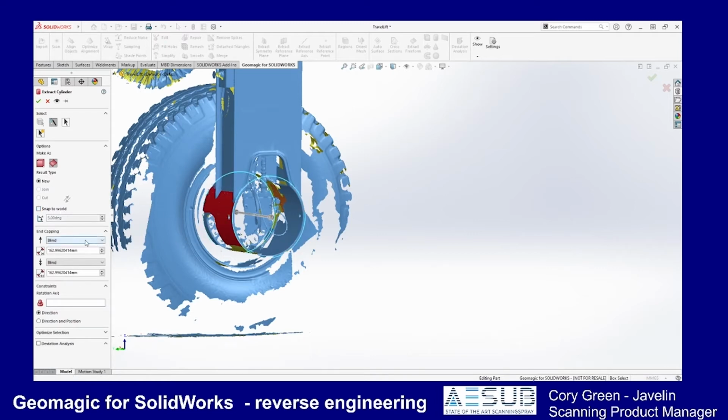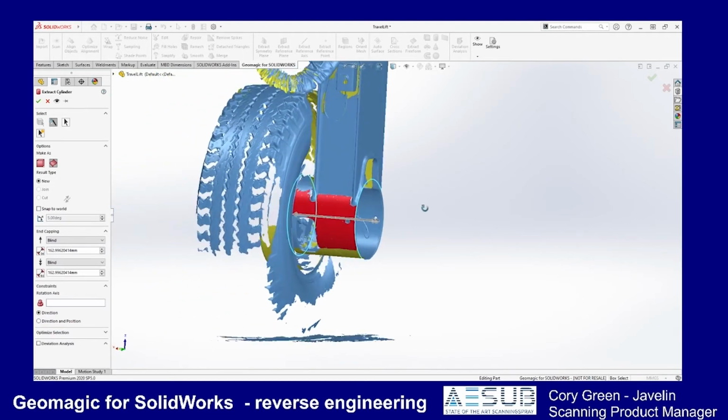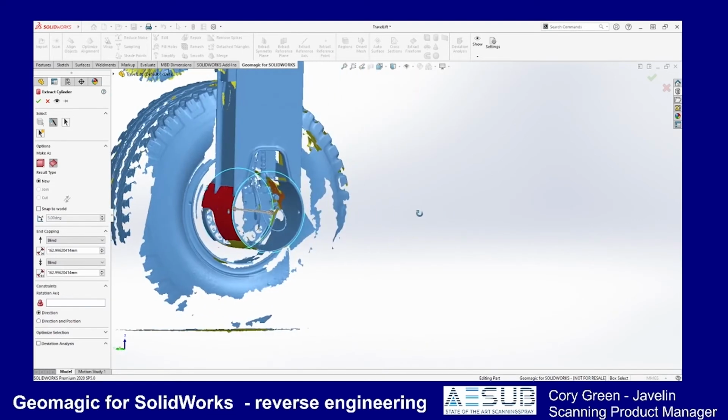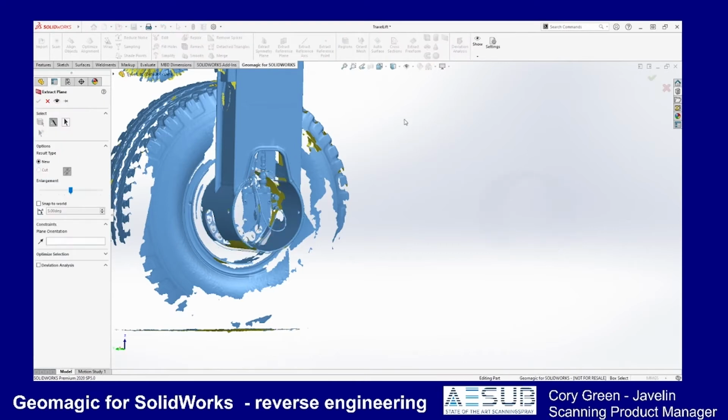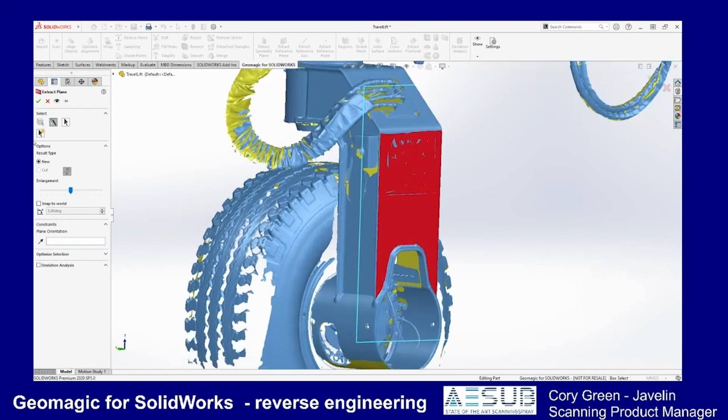We can adjust the capping of the cylinder to determine how far it spreads, and if we know what the rotation axis should be, we can suggest it. In this case, we'd like to extract it just based on the geometry. Next, we can use planar extractions to create some of the other pieces of the weldment. We'll do that now. We'll begin by selecting this forward plane.